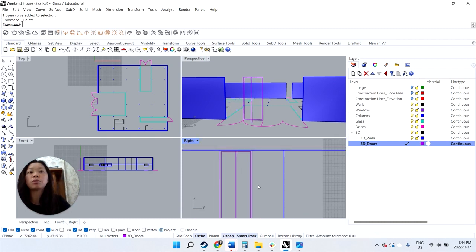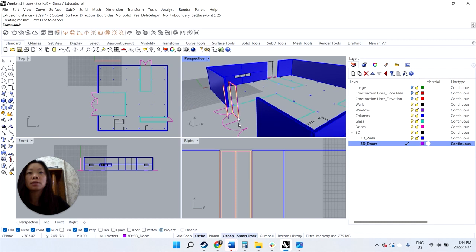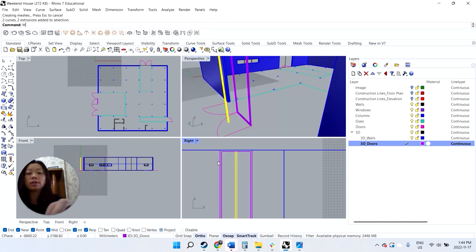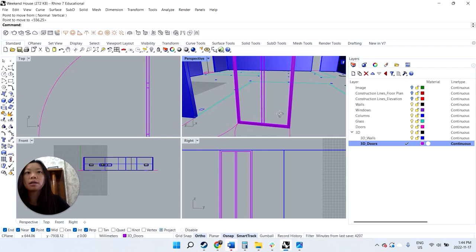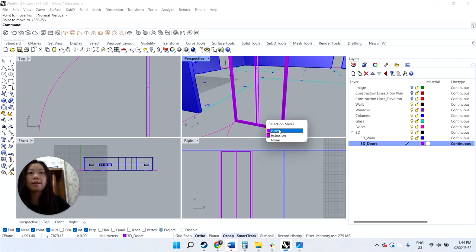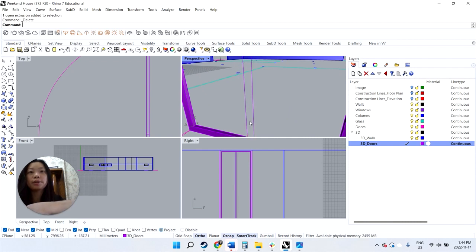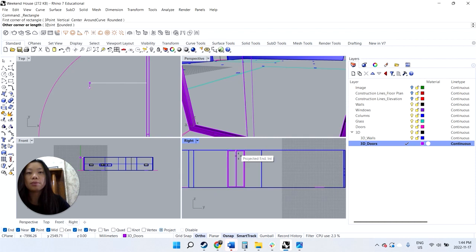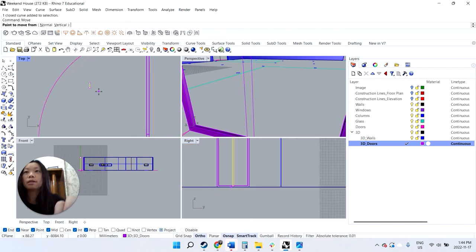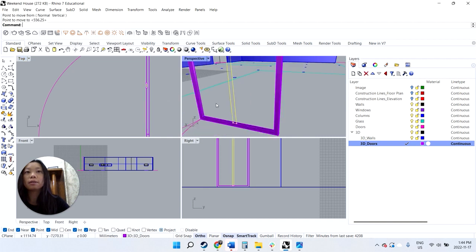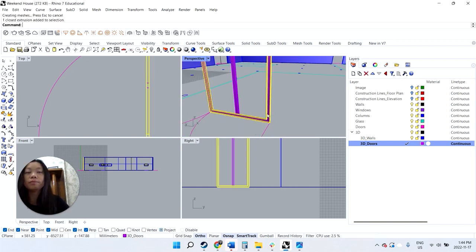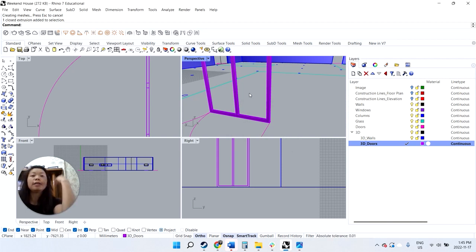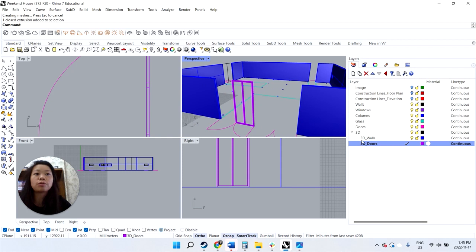And then next I can extrude curve, right? So let's select all the lines, extrude, let's say by 25. You can make sure this is again in line with the other pieces. Oh, I guess this wasn't solid because it wasn't a rectangle, so we'll need to do that. Again, move it into the plane, and then I'll extrude it by 25. So that's kind of like the door. And then that's like the door frame.